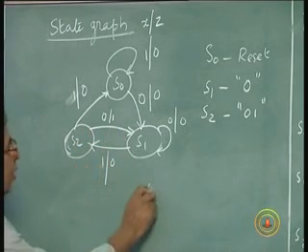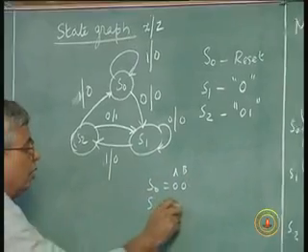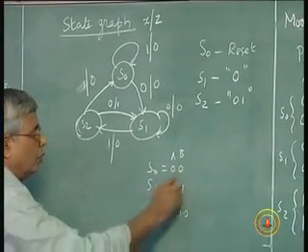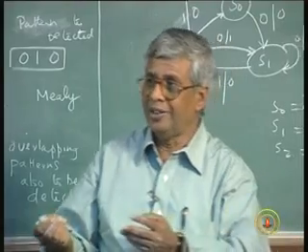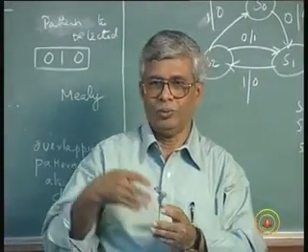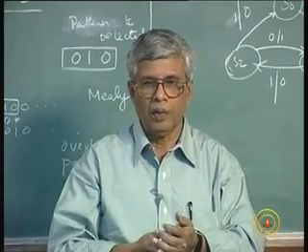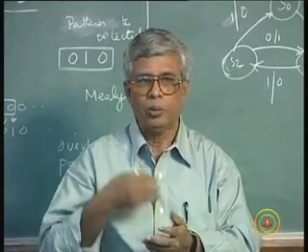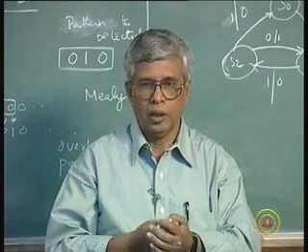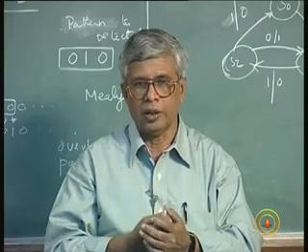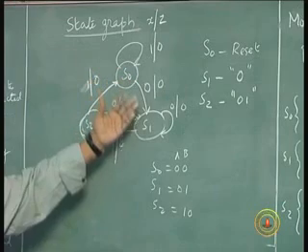For example, I can say S0 is equal to 0, 0, where A and B are the state variables, 0, 1 is S1, 1, 0 is S2, and then we can go to the state table, and then I can use D flip-flops, or I can use JK flip-flops, and I know how to draw the transition table, how to draw the Karnaugh maps, how to get the output map, how to put them together and show it as a drawing on a design sheet, and then how to translate it into hardware when you get those components. But this is the thing, the state graph formation.